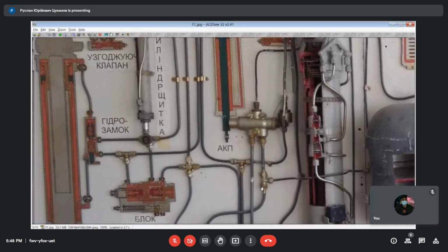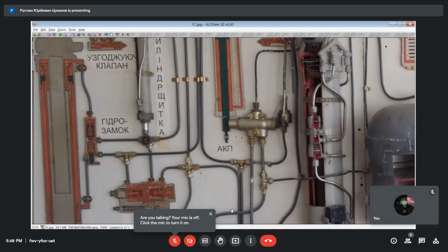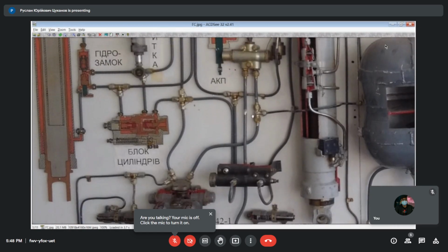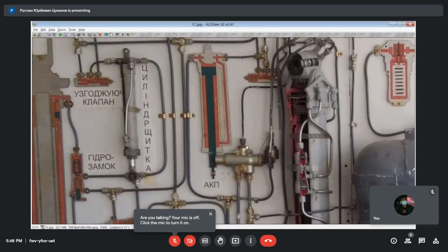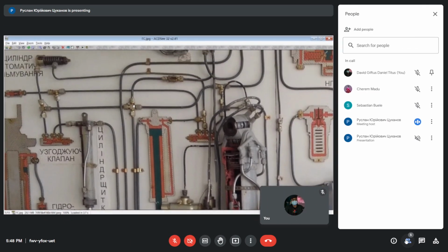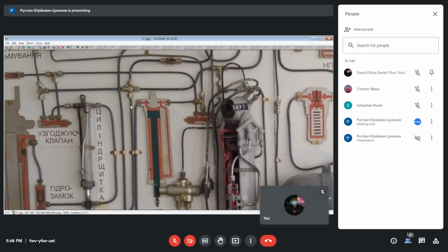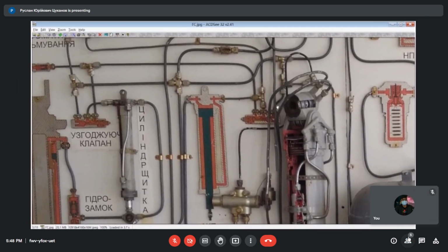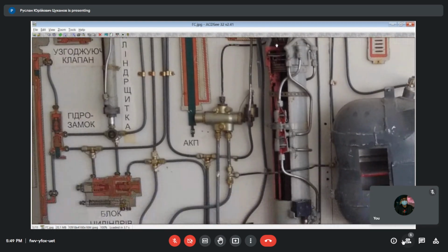First of all, this hydraulic fluid comes to, so here something is attached wrong, and I will say not as in the picture, but as it should be. It should come to this T connection. And from this T connection, it comes to the sequence valve, and only after landing gear retraction will it pass fluid to the door actuators to close the door, so we must not close the door before the landing gear is retracted.